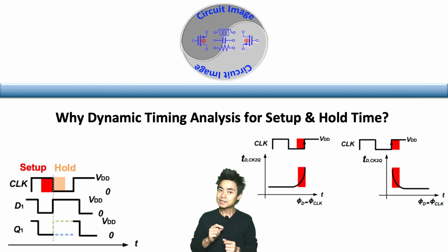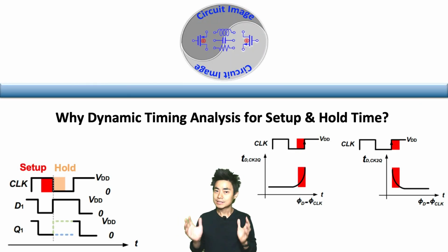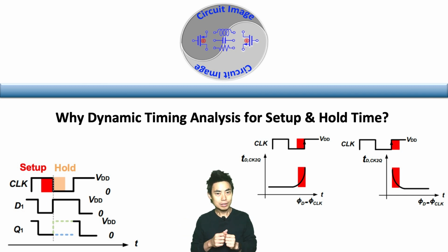After understanding the importance of the setup hold time requirements and their root cause, we must design the mixed-signal circuit with a good timing margin besides any timing variation. But it's difficult to guarantee good timing over PVT for high-speed SerDes.